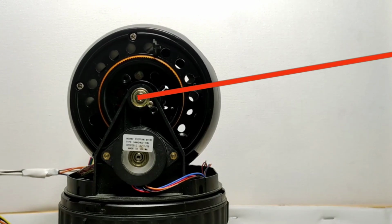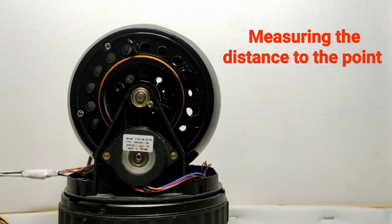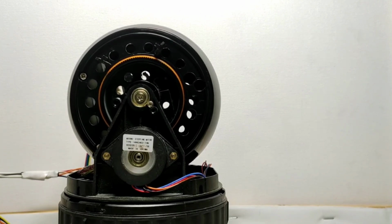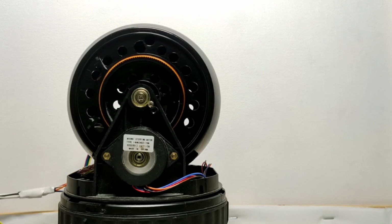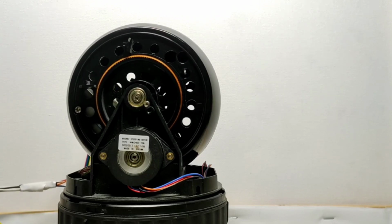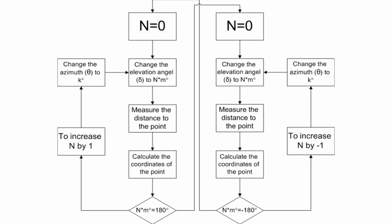More about the scanning algorithm. The prototype turned by some angle step by the elevation angle, measured the distance to the point and calculated its coordinates. When it made a turn of 180 degrees by the elevation angle, a step was made by the azimuth. After that, the algorithm was repeated, only with rotation in the opposite direction by the elevation angle. I have to add that the size of the step could be changed. More detailed description on the screen.